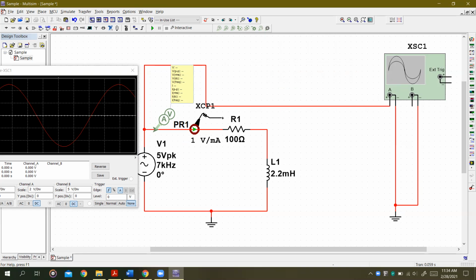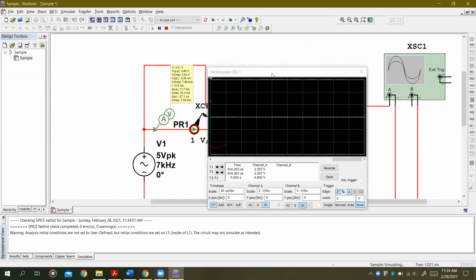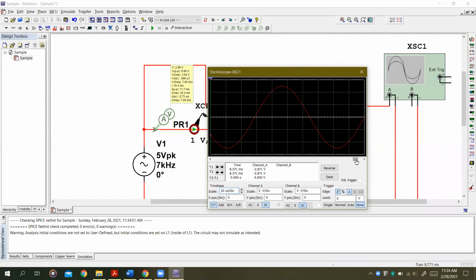Well, how do you run the oscilloscope? We open the oscilloscope, press play, and this thing runs. So since we can't observe a proper value here, we stop it and then scroll along this line. So this is the entire history of running the oscilloscope. To scroll it right, how do you change the scale? This is the time scale, that's the x-axis, and this is the y-axis. So if I increase this, it gets bigger. If I decrease this, it gets smaller.